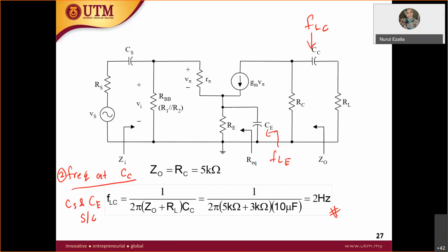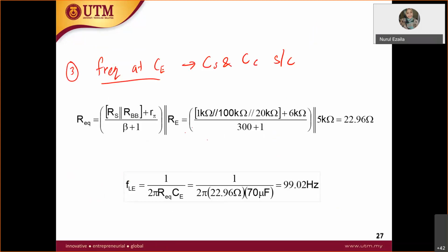From this region, you are seeing from here, so you need to apply V test, inject, find Z test, and then R equivalent equals the Z test parallel with RE.